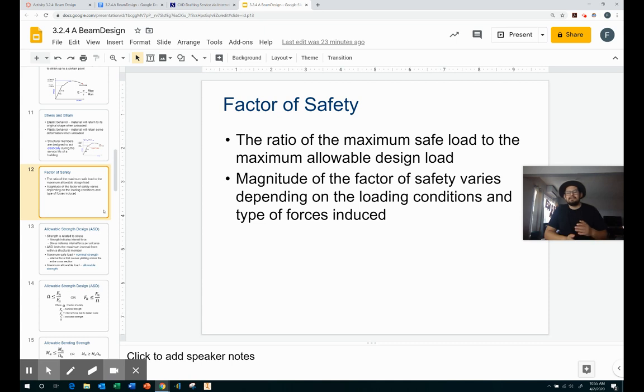So we say, okay, this has to be a safety factor of 2, which is actually a really huge safety factor. But if I were to say 2, it means you better design this to take 2 times the amount of load than what would cause it to fail. It's kind of like an elevator. When you walk into an elevator and you see maximum load of 2,000 pounds, you would sure hope there's a safety factor, because just in case they do get 2,000 pounds in there, you wouldn't want it to fail. But if you're now getting past the safety factor, it's kind of dangerous because you don't know.